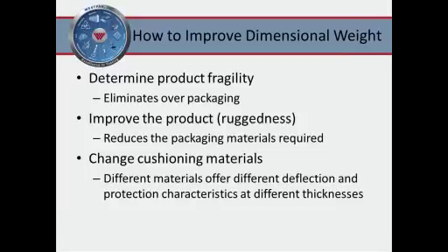And the last item that you're in direct control of is just changing cushioning materials. Different materials offer different deflections and protection characteristics at different thicknesses. I'm just going to go over 2 very, very common materials in the industry. One is expanded polystyrene, which people know as styrofoam. Styrofoam has a working percentage of 50%.